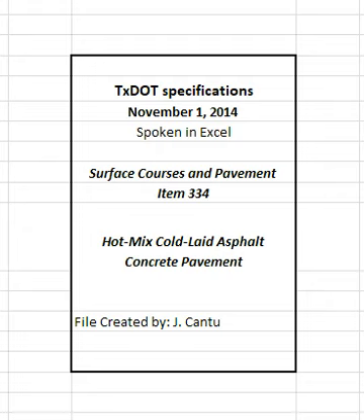Additives that facilitate mixing or improve the quality of the mixture may be allowed when approved. Provide the engineer with documentation such as the bill of lading showing the quantity of additives used in the project unless otherwise directed. When lime or liquid anti-stripping agents are used, add in accordance with Item 301, Asphalt Anti-Stripping Agents. Do not add lime directly into the mixing drum of any plant where lime is removed through the exhaust stream unless the plant has a baghouse or dust collection system that reintroduces the lime back into the drum.